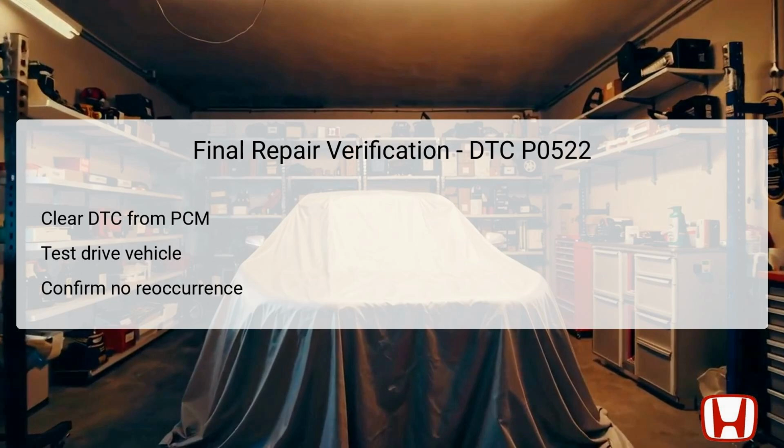It is crucial to monitor for the reappearance of the DTC or warning lights on the dashboard during this test. If no reoccurrence is noted, it indicates that the repairs made were effective and the issues related to the engine oil pressure sensor circuit have been resolved.